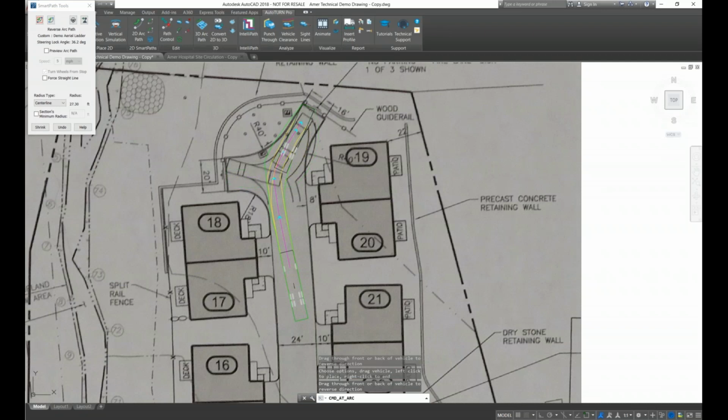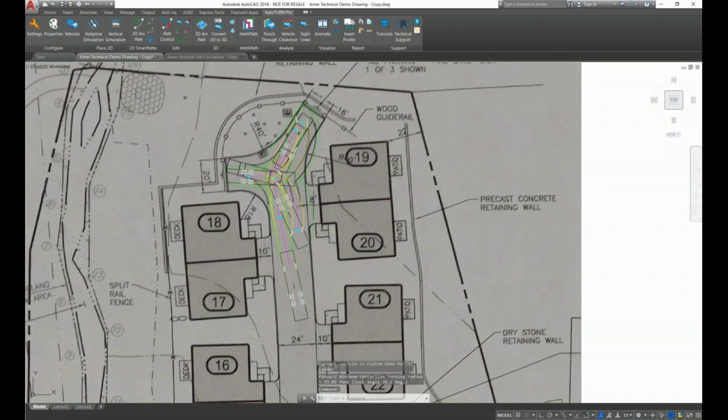So the turning capabilities are better than the single unit truck, but you can still see that even though it's not encroaching into the property, it's still blocked by the driveway. So consider in an emergency situation when the vehicle has to back up and turn out from the hammerhead, if there is a car parked in the driveway, then the fire truck would have to do multiple back up and forth, and only then it can get out of the hammerhead, which is not a desirable solution.